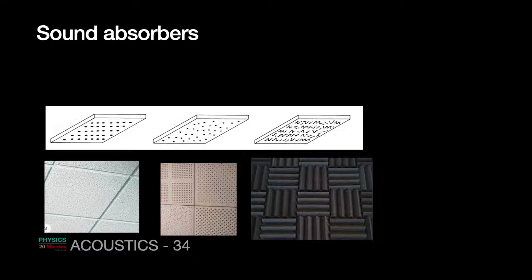These tiles are available commercially. You can just Google them and you can find a variety of them. I'm sure many of you have seen these kinds of tiles. They are placed in our college in MMR, the Multimedia Room, if you have ever been, or SCAVI, if you have ever been, then you have seen the walls are covered with perforated tiles. That's how they look. People sometimes make false ceilings with perforated tiles, etc. These are zigzag, perforated plus zigzag. Zigzag tiles increase the surface area and therefore increase the absorption of sound manifold. So sometimes even these are preferred.